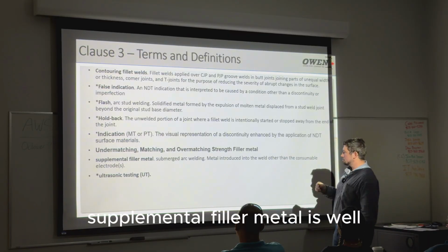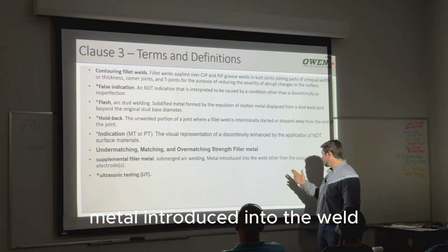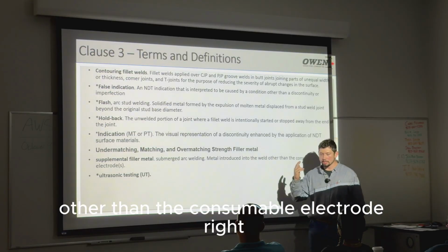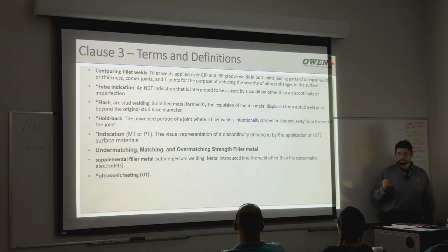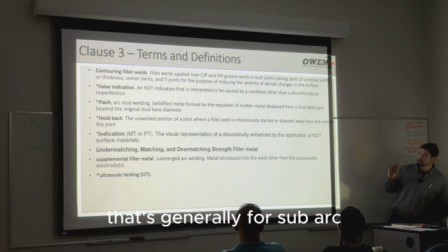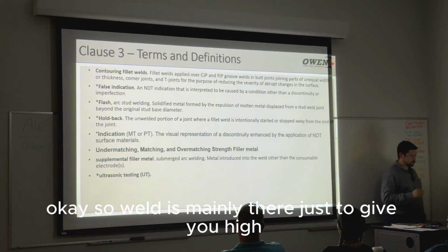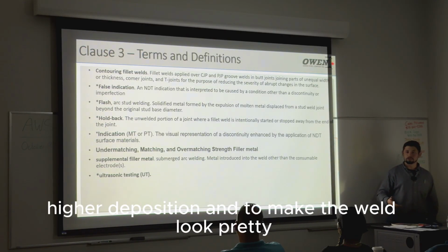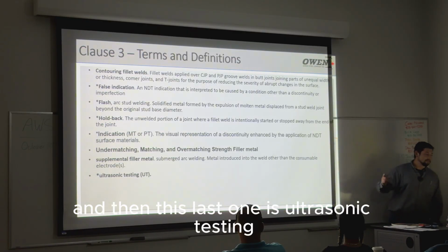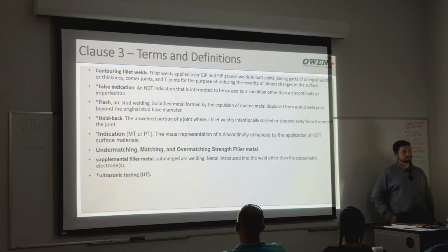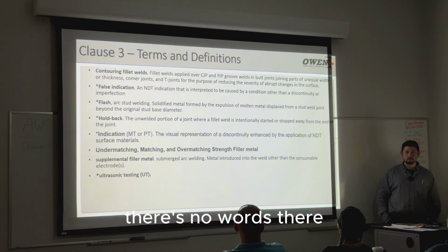Supplemental filler metal is metal introduced into the weld other than the consumable electrode, right? That's generally for sub-arc. So it's weld that's mainly there just to give you higher deposition and to make the weld look pretty. Right? And then this last one is ultrasonic testing. There's no words there.